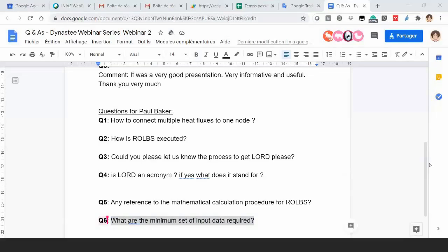But if you are carrying out these kind of measurements, then I know the standard on in situ heat flux measurements recommends, I think, 72 hours of data, but I've carried out lots of heat flow measurements, particularly on older buildings, and you need 2 weeks of data to get a reasonable result because of the thermal mass of the walls.